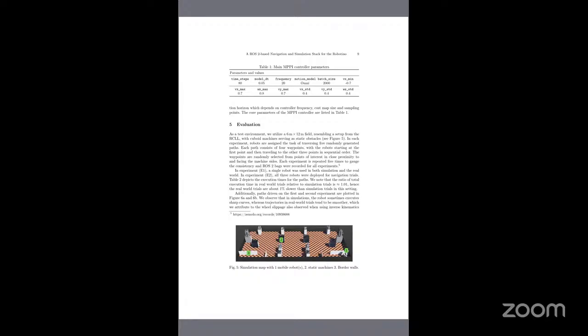So every prediction there will be a time limit. There will be a waiting time, right? That means 0.05 seconds, that means 50 milliseconds. That means delay time. Frequency 20 hertz. Every 1 second, the controller will give new command.